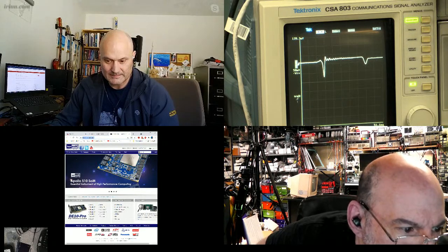Ontario says hello. Do FPGAs do rerouting of portions on the fly? Yes. The question is, can you reconfigure an FPGA on the fly? And yes, there's IP made that allows it to rewrite itself based on what you're doing. So I can't even tell you to be careful. It just makes sense to reburn some of your FPGA on the fly if you're so inclined, but you have to know what you're doing. And the part has to be willing to do that. It means portions of it can be rewritten from the other portions which are static. So it's not like you have to dump the whole array. You have to dump just part of the array.